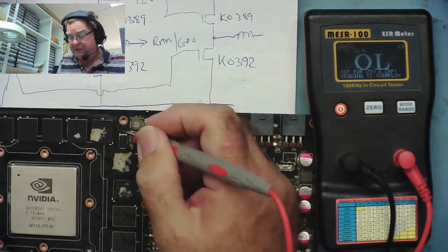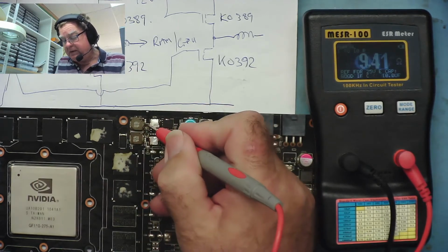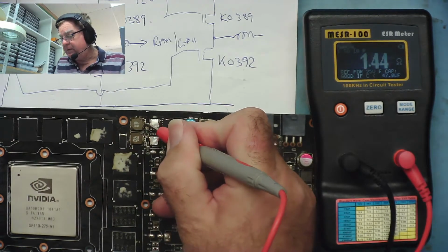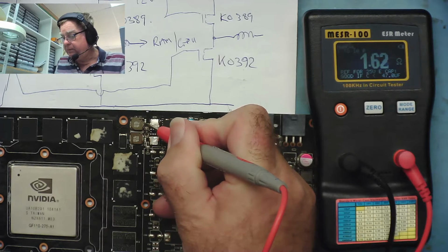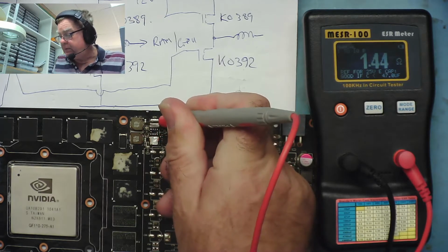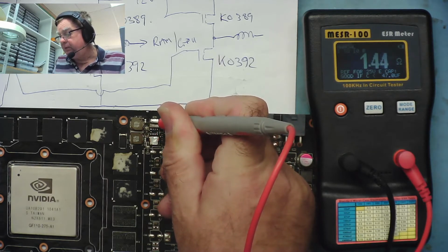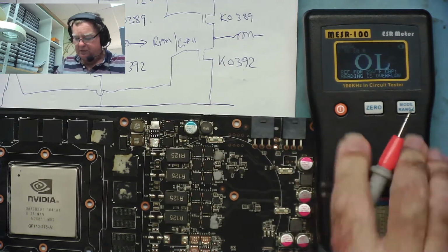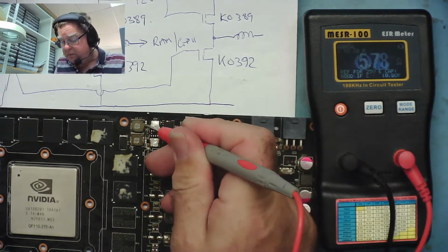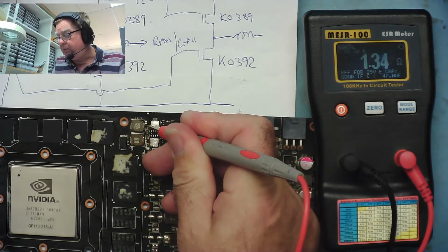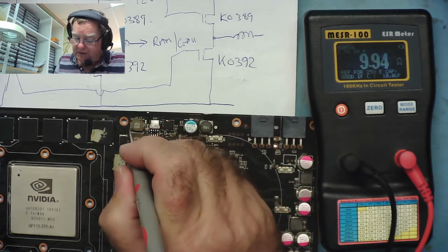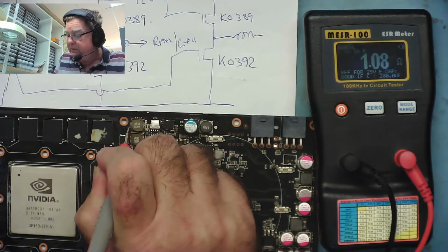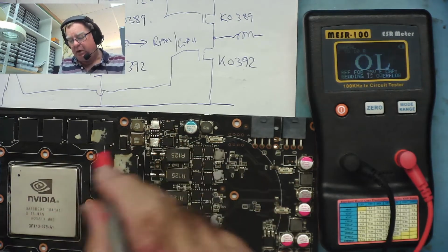What I saw on that capacitor, because it's the same rail. And this side, I was seeing more. Well, I need to settle down, about 1.4, 1.44, 1.5. I think the contacts on this are not the best, but anyway, I definitely have more this side, 1.33, than I have this side. And I'm sort of saying, well, the low resistance is on this side.